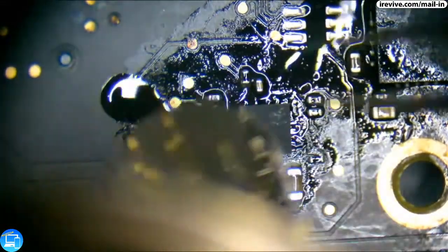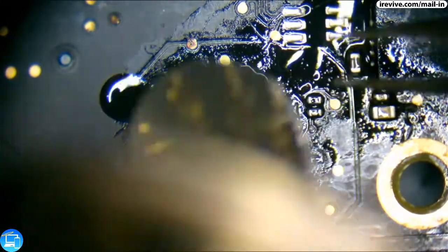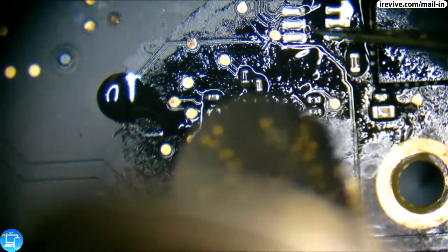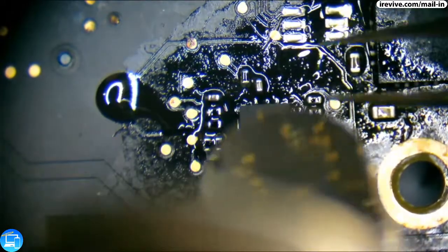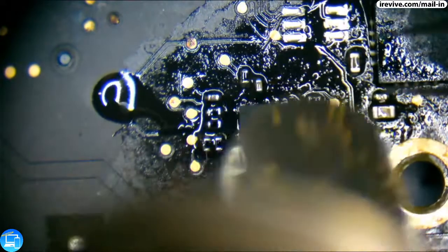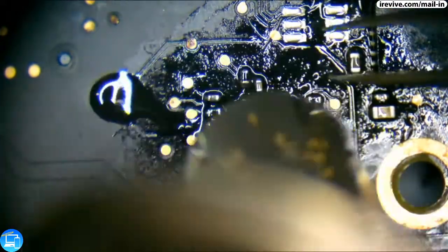So whenever you're doing something like a BGA rework, you want to have your air output in just a lower throughput. If you blow it too hard, the chip will go into your fume extractor and into the ether. You want to know how I know?